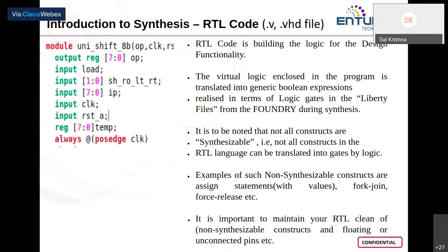If you just want to write a code and simulate it to check the functionality, you can write it with any of the constructs that are available with Verilog or VHDL. But if you want to synthesize your code, then there is a set of constructs that are recommended to be avoided. You should not use them. All such constructs are called non-synthesizable constructs. So what are synthesizable and non-synthesizable constructs? As I said, during synthesis, especially in the mapping stage, every instruction or block from your RTL code is mapped to a particular subdesign which has the exact same functionality.